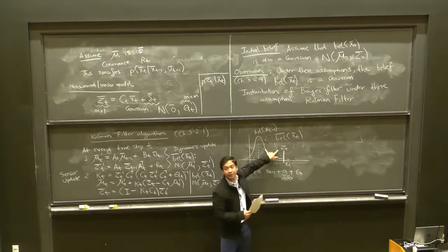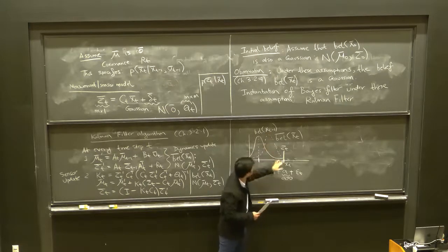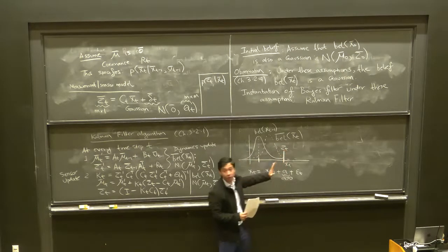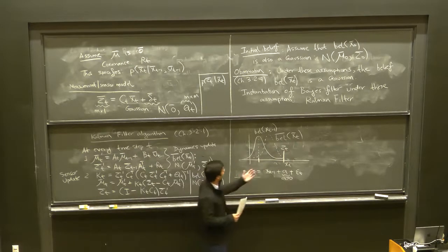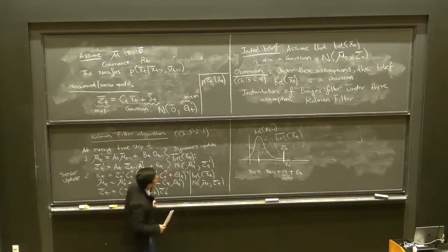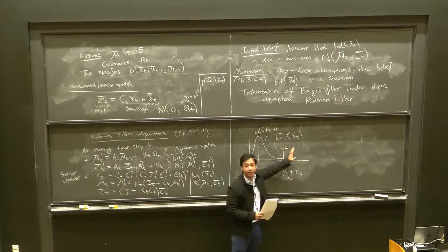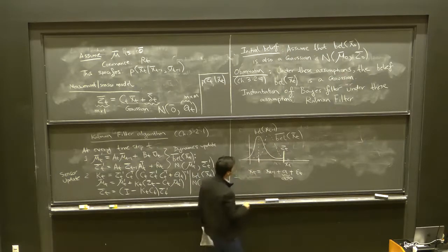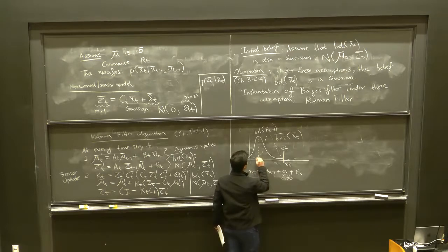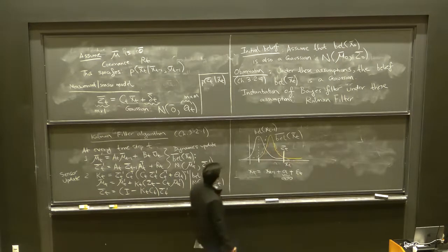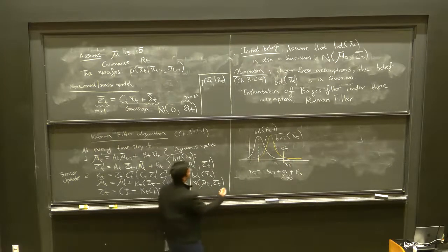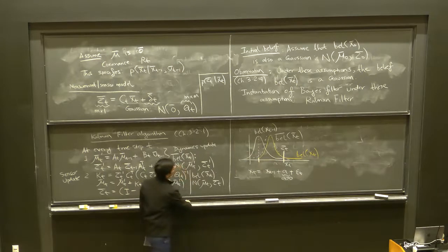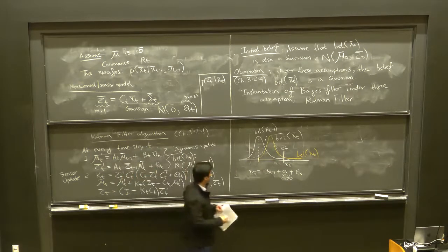Before we take into account the sensor measurement, we have this belief, the dotted line. Now our sensor measurement is saying that the sensor thinks this is the state. But of course, we know that the sensor is not perfect, so there's some uncertainty associated with the sensor measurement. But the sensor is giving us a hint that the true state is actually further to the right. So once we do the update, we're going to get something that looks like this, in orange chalk. Maybe we shift the belief bar a bit to the right, and we might shrink our uncertainty a bit.